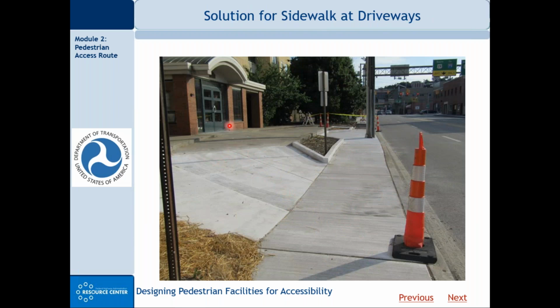This is a kind of medium rise residential facility. This is not the main entrance. This is sort of a pickup and drop off. And so really all the vehicles that are using this would be pickup trucks, SUVs, passenger car automobiles. And so I think they can probably navigate that grade break okay, but a commercial type vehicle may not be able to, but the commercial access is in the rear of the building.